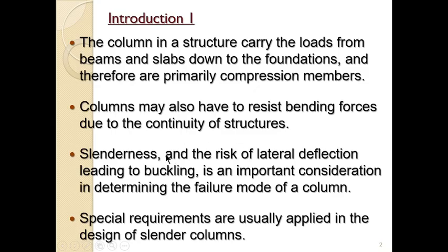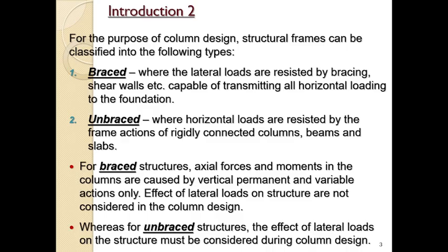Now, slenderness is a critical factor in columns because some columns are slender, and because of slenderness they tend to have lateral deflection, which can lead to buckling. So we need to consider the issue of slenderness when we are designing a column. Special requirements are usually applied in the design of slender columns that are different from the design of columns that are considered short.